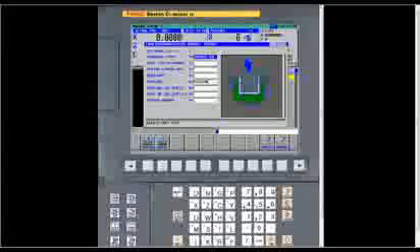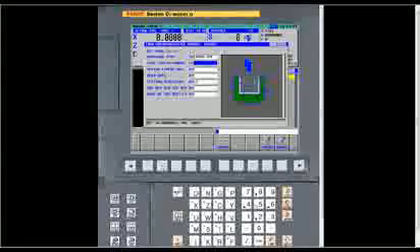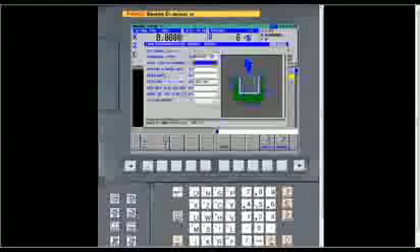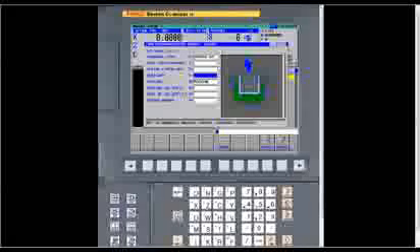If you want to use layering, what that does, it only takes layers out. It'll go down so far, rough it completely out, go down a little further, and rough it completely out. That's how that works. But if we use center cutting, then you can leave a certain amount of finish stock. You can see both of these next two fields have asterisks where you don't have to answer that information.